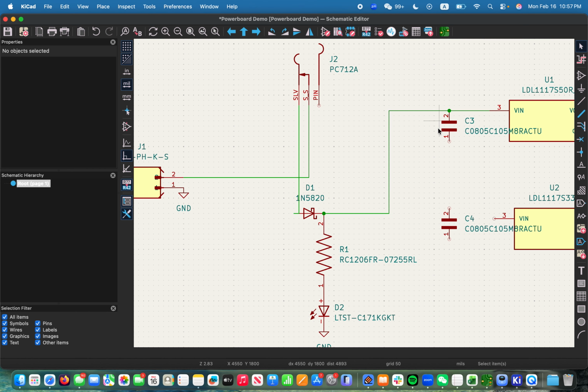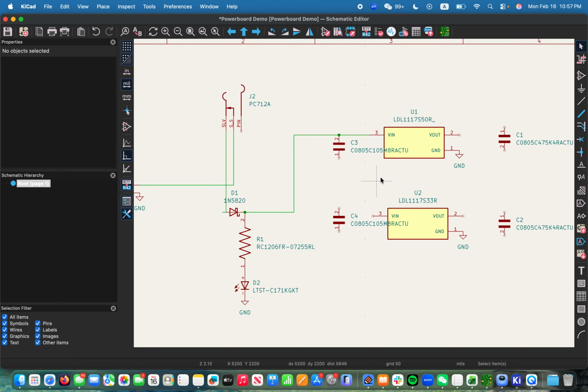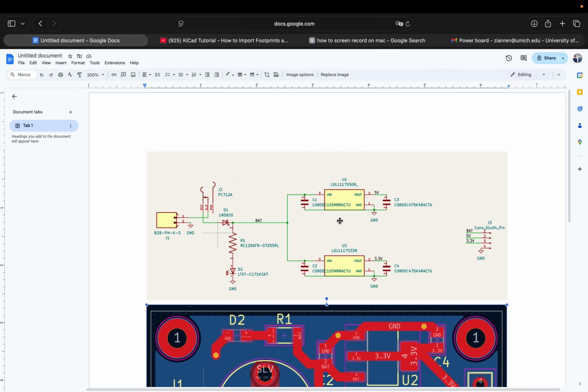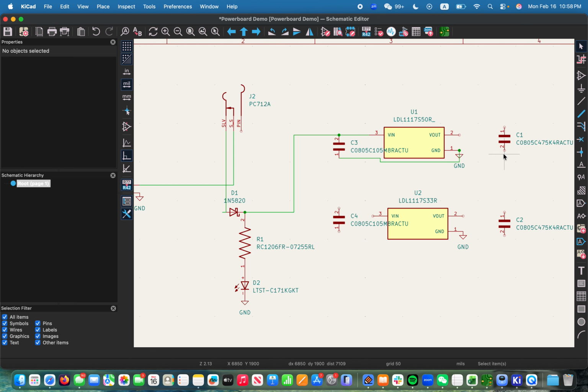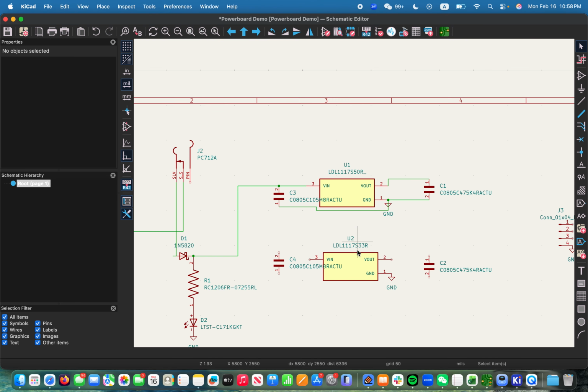And then this is really convenient. I've placed the capacitor in the right place, so that's a node formed there, and I just need to connect that node with the ground. So let's go ahead and do that. Make sure that node symbol pops up, and then let's do the other side of these capacitors. So this end will go to ground, this end will go to V out.